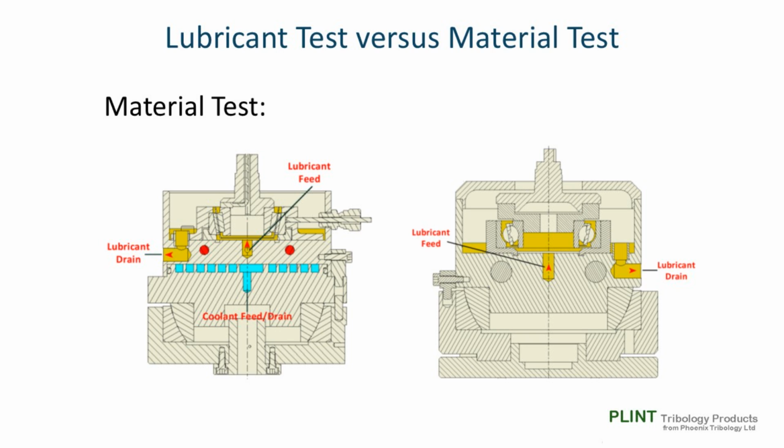It follows that for a test of the material properties or bearing design, lubricant should be circulated through the test assembly from a large volume source, which includes filtering, such that changes to the overall lubricant properties are limited to those associated with temperature viscosity effects within the test assembly, and not other properties associated with exposing the lubricant to temperature and mechanical shear.